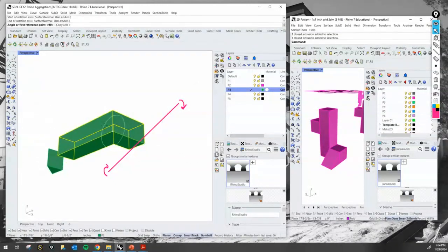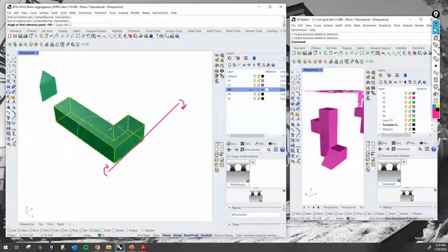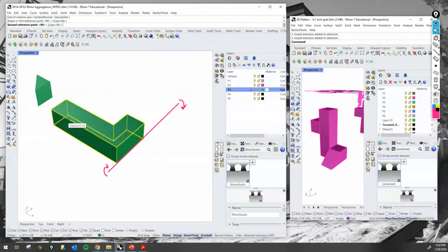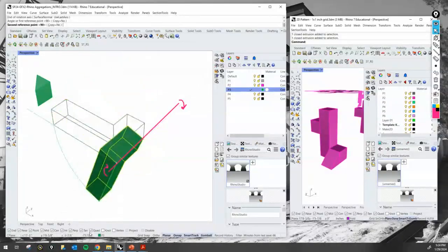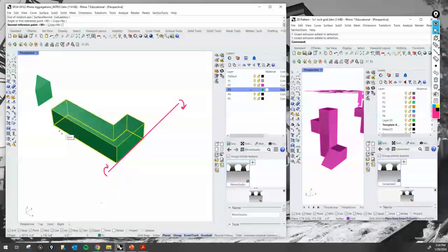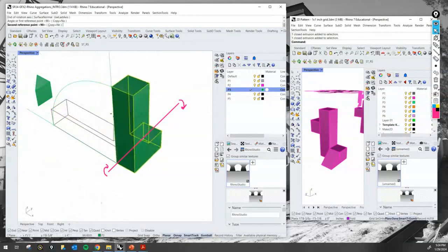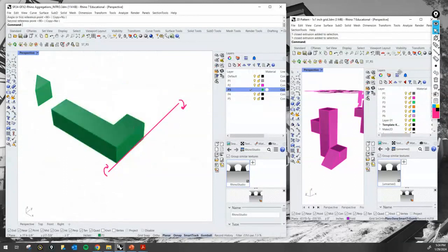It gives me that circle right there, because now what I'm going to tell Rhino is, hey Rhino, that's my axis, and I want you now to rotate from that point right there. It's technically 90 degrees, and you actually can see it underneath right here on this portion of the screen, right? Because that's laying down, and we actually need to bring this 90 degrees up like that.